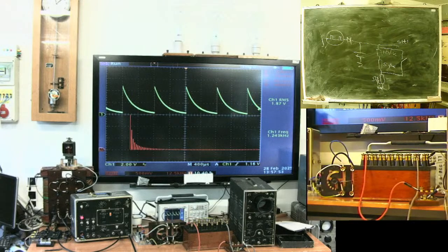Here is how it is. So first, the higher the distance between pulses in time, the shorter the space between spectral lines. Point 1, point 2. Our conclusion: the faster rate of change of the pulse means a longer spectrum. Slow change, short spectrum. It's very important when you deal with power electronics.